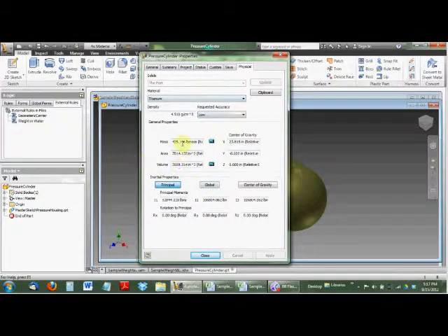We're taking these masses and volumes with our iLogic rules and using them to create information for a spreadsheet that can determine basically the behavior of an object submerged, which is a weight and balance. So that means we've got stability information, the separation of the center of gravity and the center of buoyancy, and we also know whether the object will either sink or float, which is important.